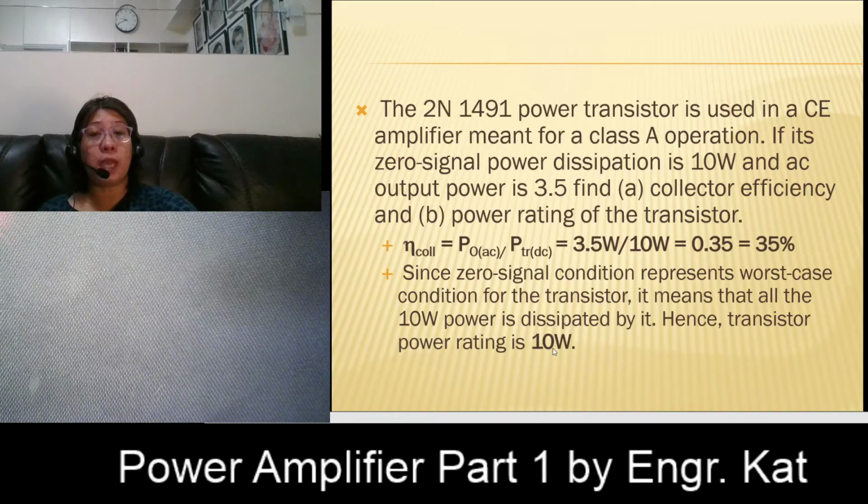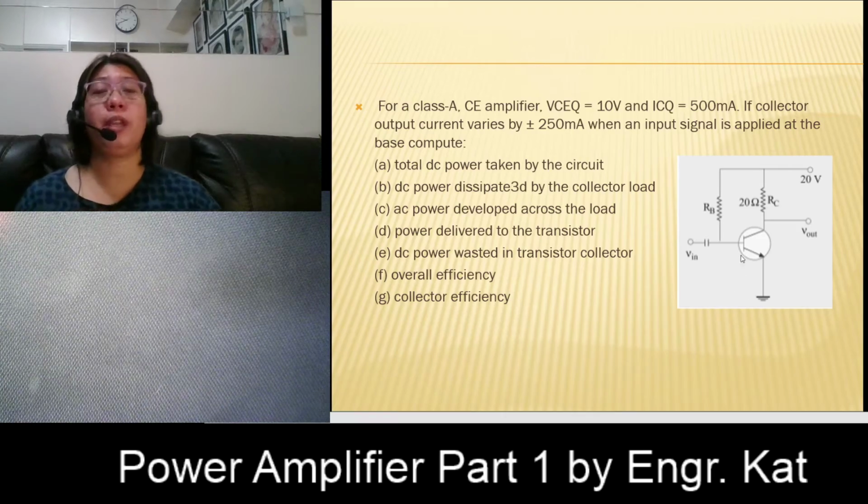Because if you use a 5 watts transistor for this, and at zero signal power it receives 10 watts, therefore your transistor will be destroyed. So therefore, it must be 10 watts or at least, or much better, greater than 10 watts. Okay? So let's have another example.